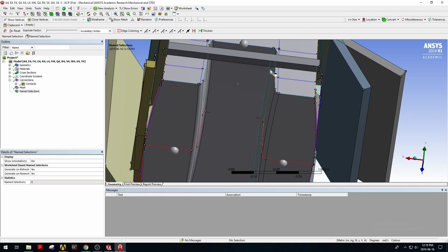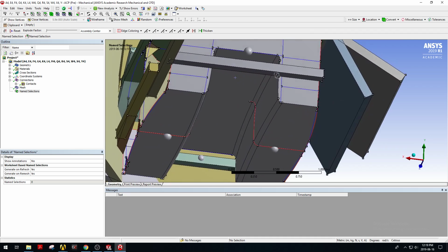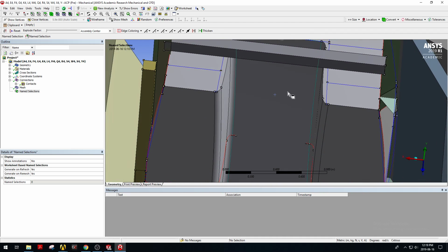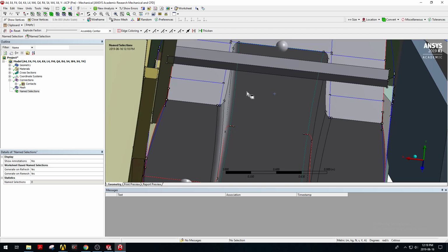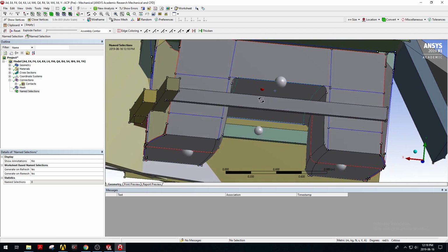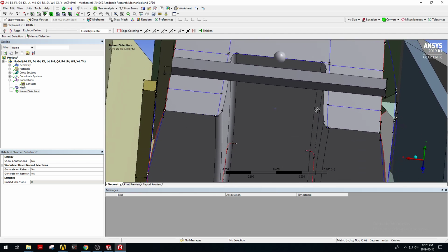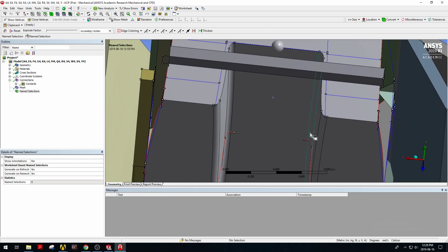For example, with the bottom panel, we are planning to make the center part a bit thicker, with more layers of carbon fiber than the bottom panels. The reason is that because of this shape, it will sort of act like a spring, and we want it to be super rigid, so we're going to add some extra carbon fiber here.